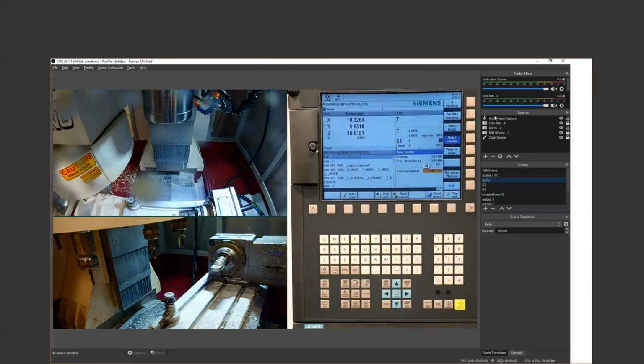And there you go. I had slowed down a little bit, so we were at 6:48, 7:18, and you said in NX we were around 5 minutes. So certainly we can start to see how, between using NX and then mimicking that with our digital twin, we can really give you some solid real data that's coming in. And certainly I would say the 20-second, 30-second cycle time discrepancy I have there would be my tool changer for sure. These carousels are great. They're rock solid, but they're not known to be the fastest things in the world.